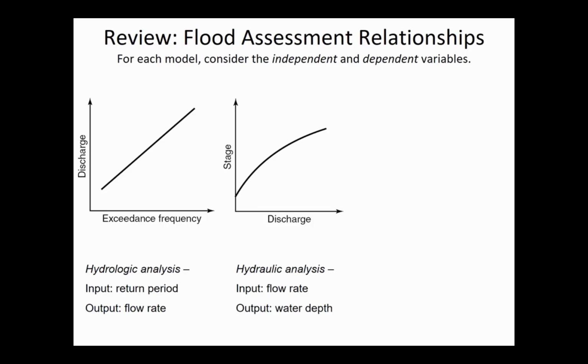You remember at the end of hydraulic engineering last semester, we were doing open channel calculations like the numerical integration method, the standard step method, where you were taking a known depth at a certain location and working upstream by looking at the slope of the energy grade line and the channel slope, so you knew at a certain distance upstream what the depth would be for a flow rate. And so this curve is just for a flow rate, how deep is the water? And you run it for a lot of different flow rates.